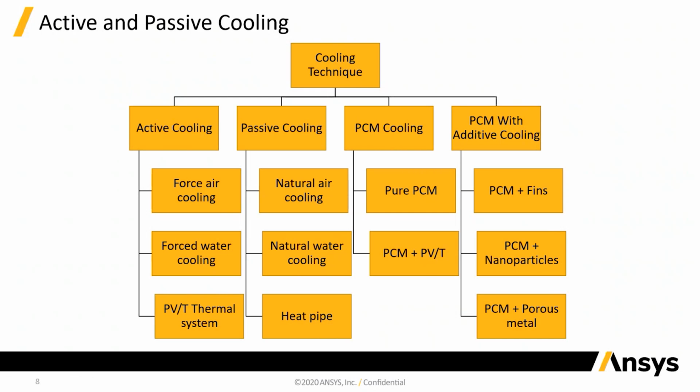It uses latent heat to absorb more heat in a shorter space, and then finally it dissipates it to the air. The next type is the phase change material. Typically, this phase change material talks about a solid to liquid kind of phase change. It is basically used as an absorber. So maybe for a system which works at high dissipation only for a certain amount of time, that is where these phase change materials are used.